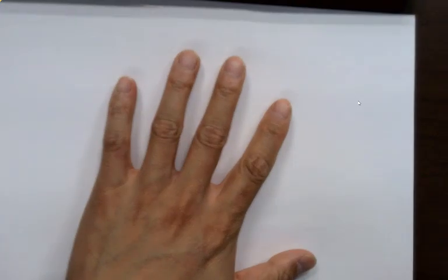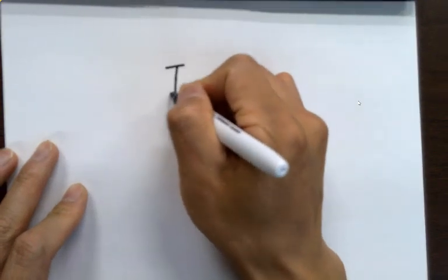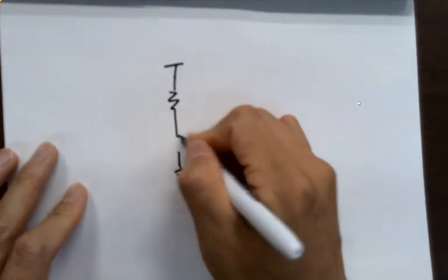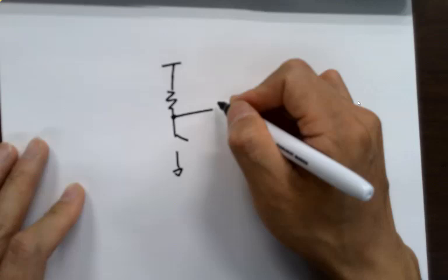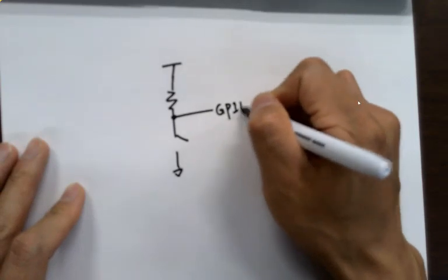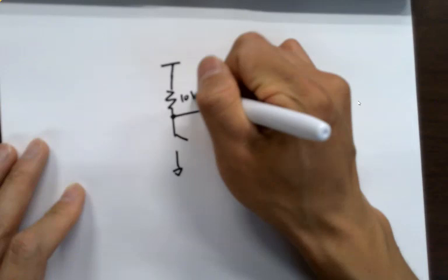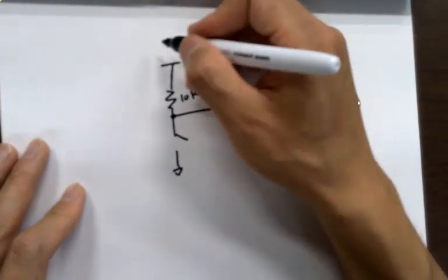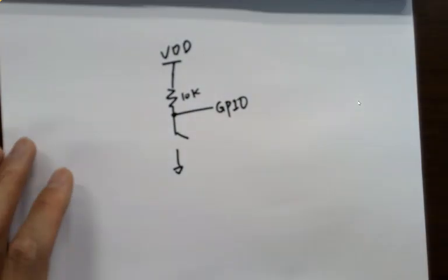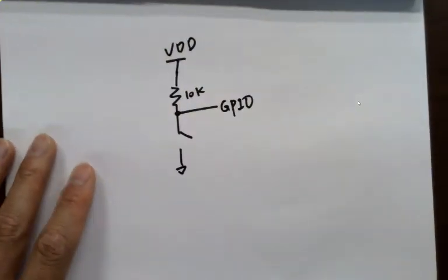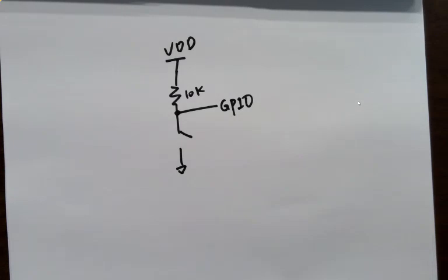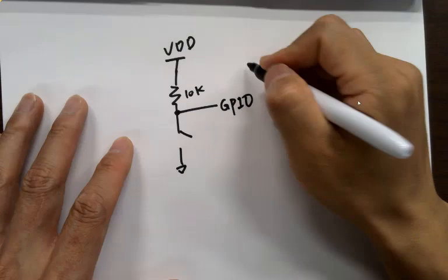Before I do anything, let me ask you a very simple question, circuit 1 question. What is GPIO? Yeah, it's the I/O ports for the digital circuit, right? Focus. So what's the name of the 10K resistor? What's the name of it? Yeah. Pull up. Why?